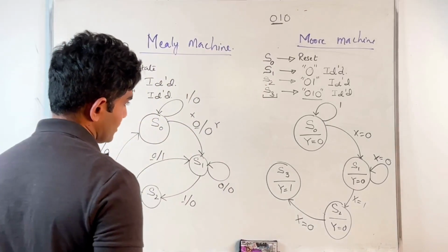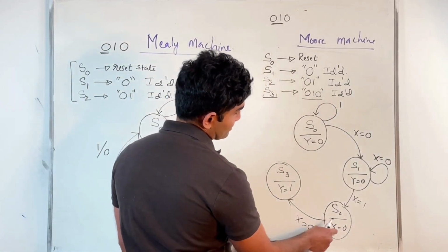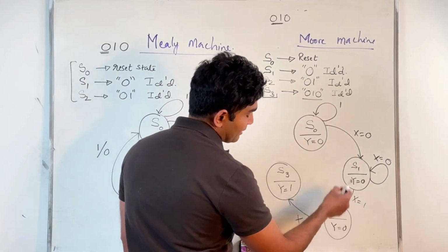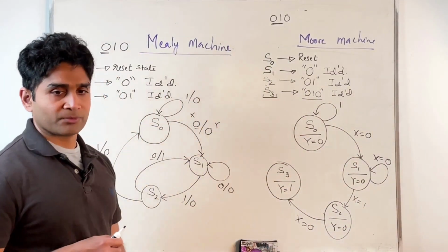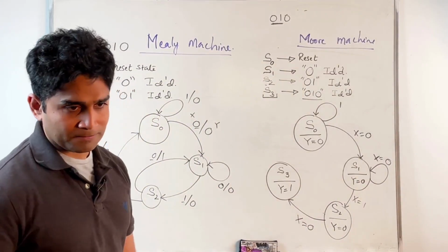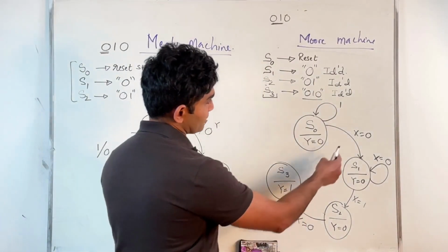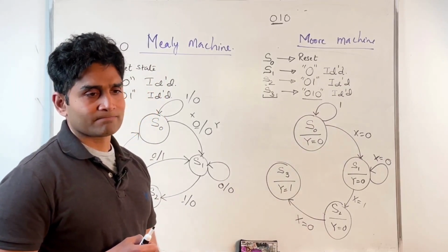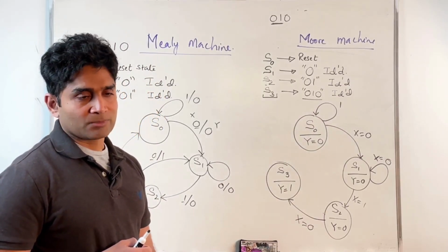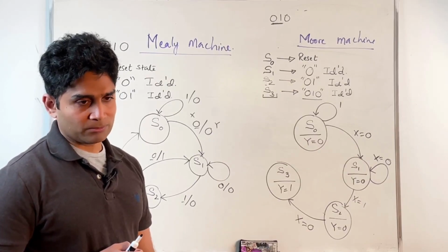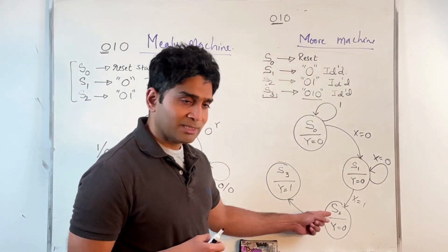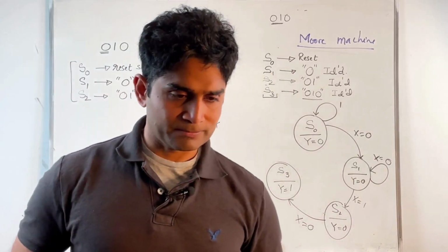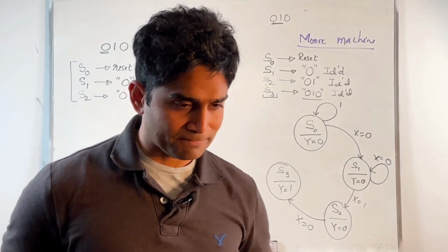All right. Now I'm in this state. That means I have identified 0, 1 in my input stream. X equal to 1 occurs now. What should be my state transition? That means I have something like 0, 1, 1 in my input stream. Where should I transition to now? When I'm in the S2 state, and x equal to 1 occurs in my input stream.